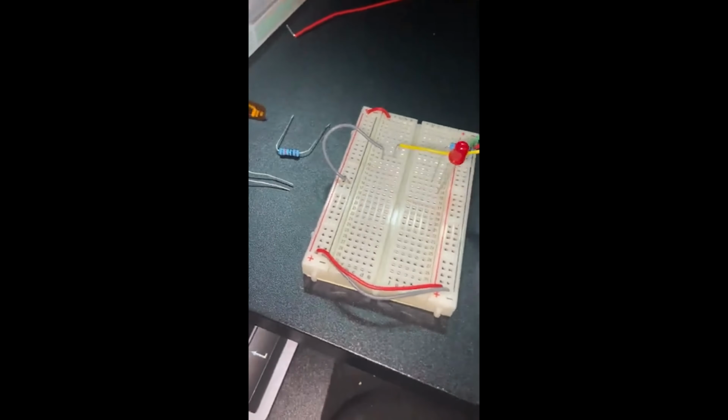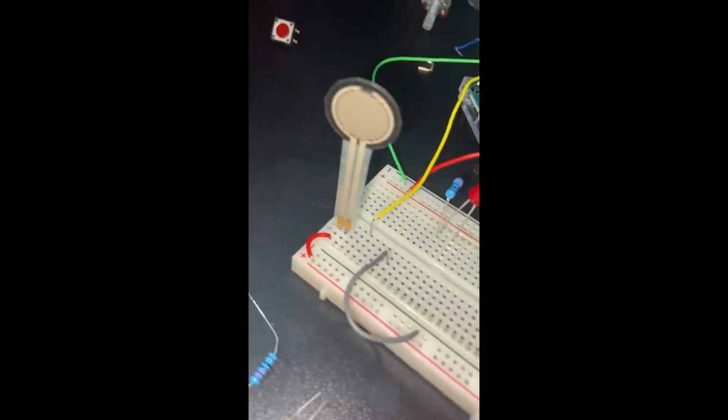So I'm just going to put it in right there. We're going to go to positive. It's going to go, again, through the sensor and out to that side. So we have to do 2 things. Again, if you remember from the diagram that I will put back on the screen as soon as I scroll back up to it, we have to have two resistors and one of them changes. We already have the changing resistor here, so we're going to use this one, this 10k ohm, as a fixed resistor.